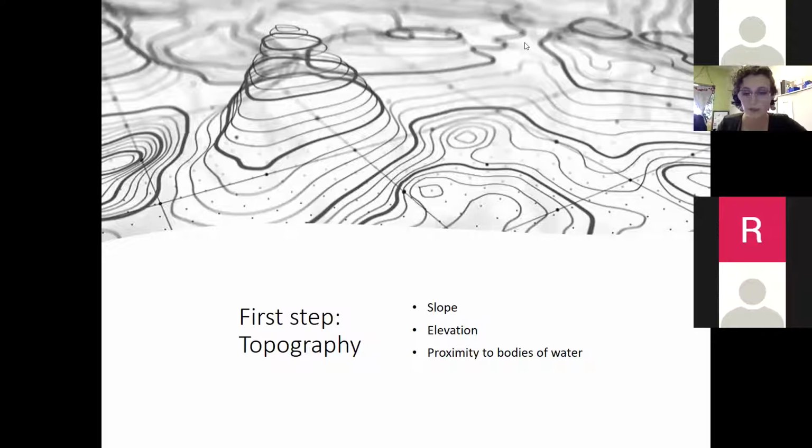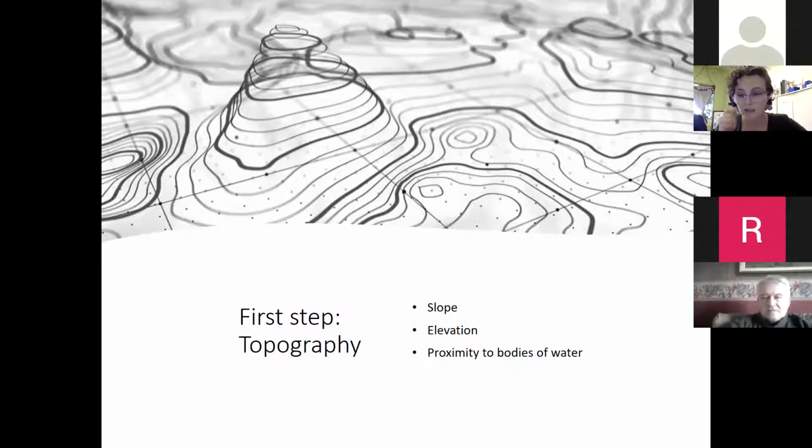If you have an area you really think could benefit from a rain garden, however, that has a steeper slope, you can always consider building a berm, just for the purpose that the water will be held in the garden and won't run off, which defeats the purpose. You also don't typically want to build gardens on top of mountains. You want to catch the water in low-lying areas that will catch the surface runoff to help it infiltrate into the ground before it reaches streams and other bodies of water. And of course, groundwater reserves.